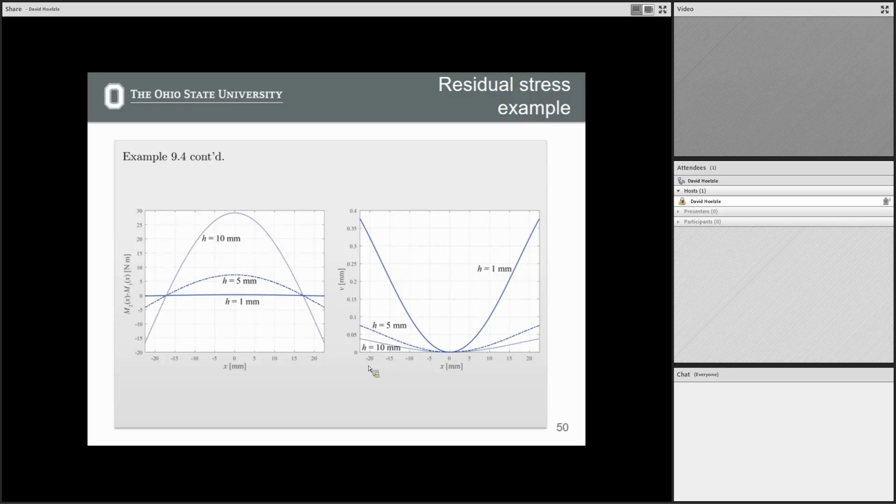So it depends on what your manufacturing specifications are. 50 microns may be acceptable to you, it may not be. It depends. That's pretty small though. That's getting on the order of the roughness of your part when you get to 50 microns, right? But getting close to 0.5 millimeter, I think that's out of spec for a lot of engineering requirements, right? That's pretty high.